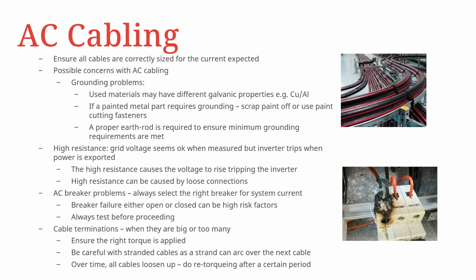Another important note is over time, all cables loosen up, and that's why you do retorquing after a certain period. So obviously the cables heat up and cool down, and this causes those connections to sometimes get a bit looser.